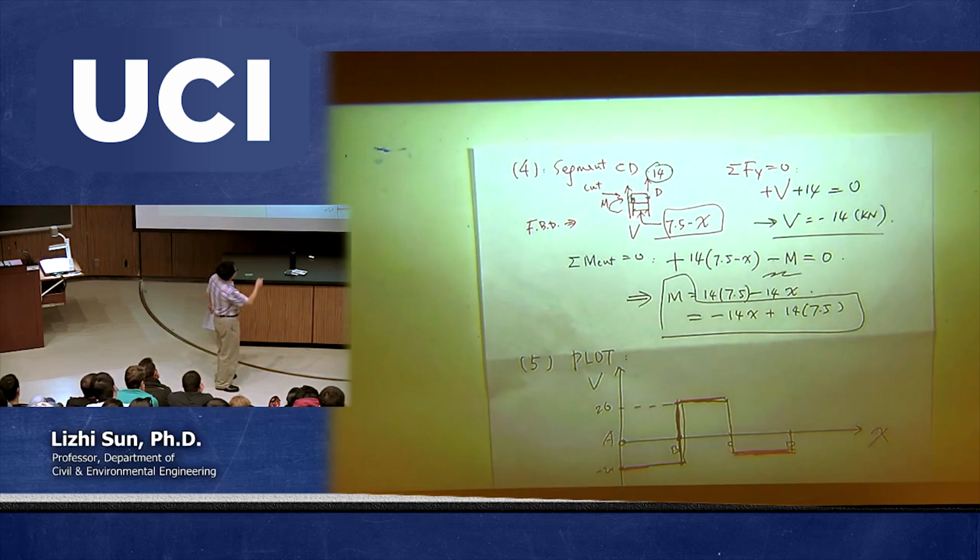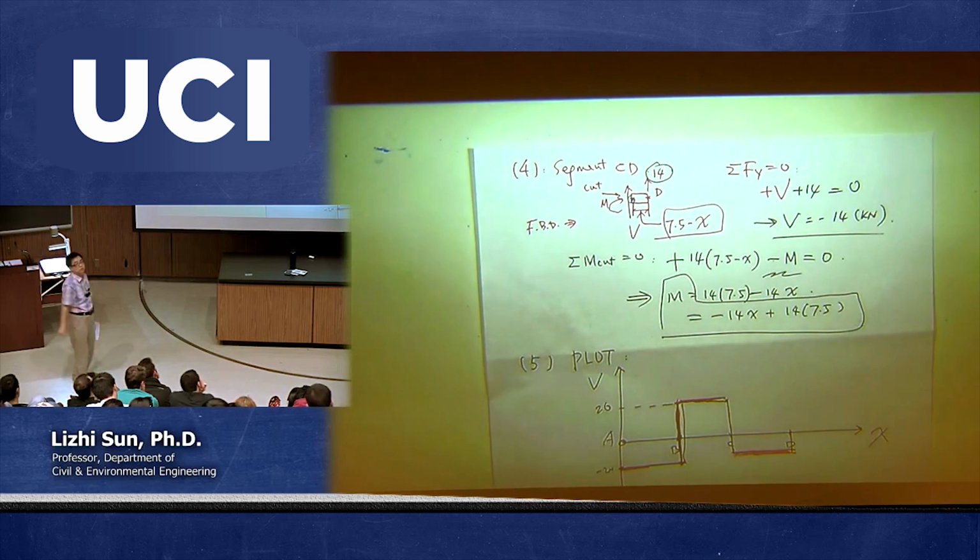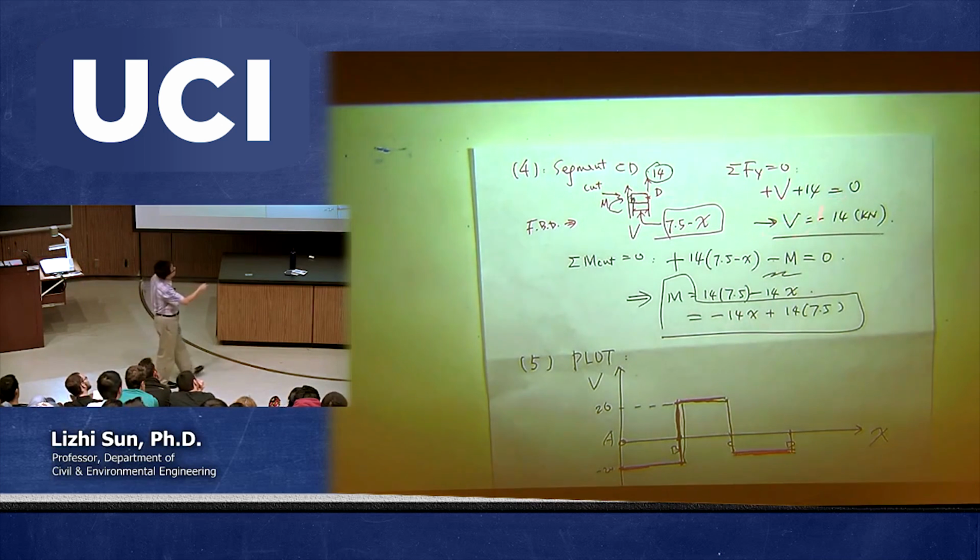So with this new free body diagram, again, in order to calculate the shear force, I need to collect all the forces in y direction. That's always the case. Okay? And then you just add all the forces, you get the shear force calculated.